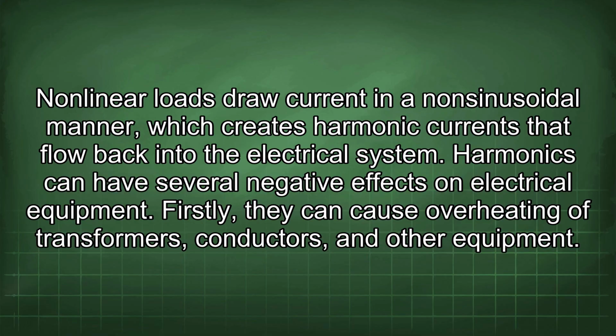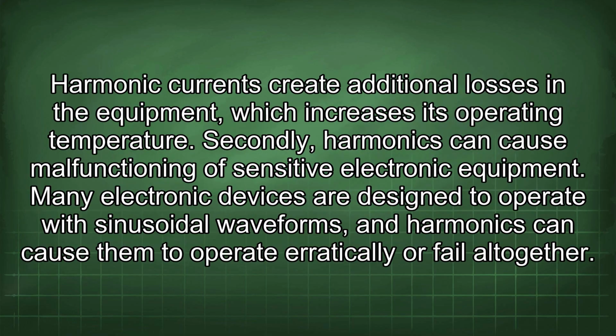Harmonics can have several negative effects on electrical equipment. Firstly, they can cause overheating of transformers, conductors, and other equipment. Harmonic currents create additional losses in the equipment, which increases its operating temperature. Secondly, harmonics can cause malfunctioning of sensitive electronic equipment.